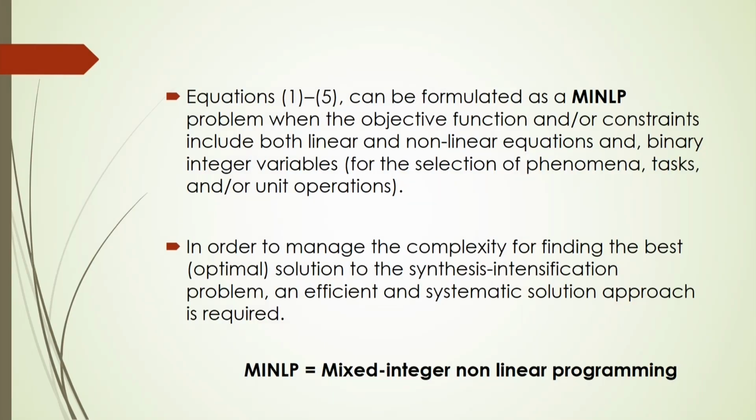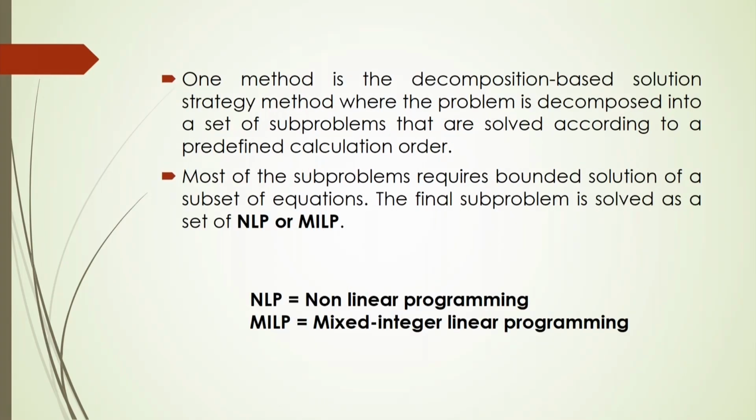So, this MINLP problem should be considered when the objective function or constraints include both linear and non-linear equations, and also binary integer variables for the selection of phenomena and tasks or unit operations to be considered. MINLP is mixed integer nonlinear programming, and one method is the decomposition based solution strategy, where the problem is decomposed into a set of sub problems that are solved according to the predefined calculation order.